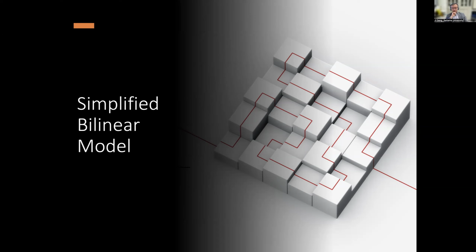So you need to learn the step-by-step approach of if and else, elastic domain, plastic domain, the conditions that just set them one by one. So it works. But for the case of bilinear model, because it's very simple, we have a very simplified method to do this simulation. That's why a lot of people love to use the bilinear model, because they can program it very simply.